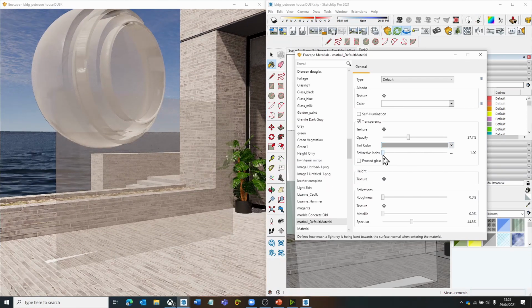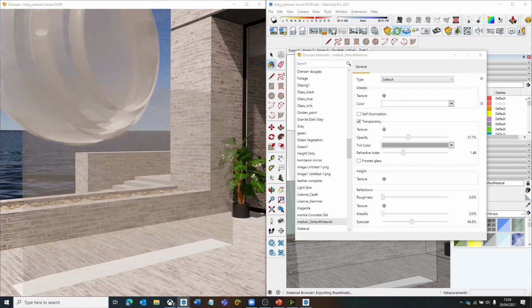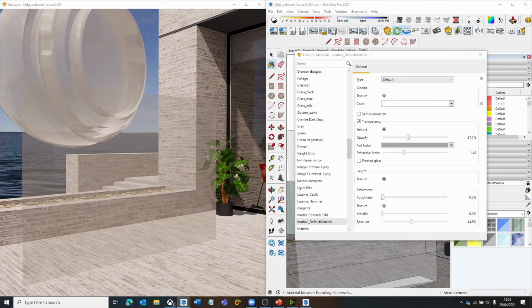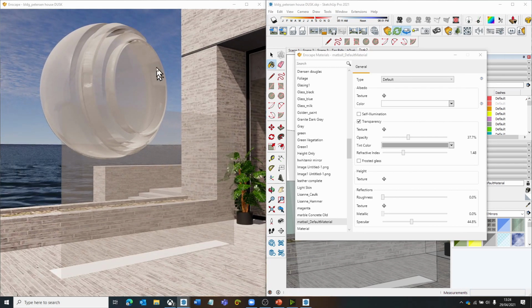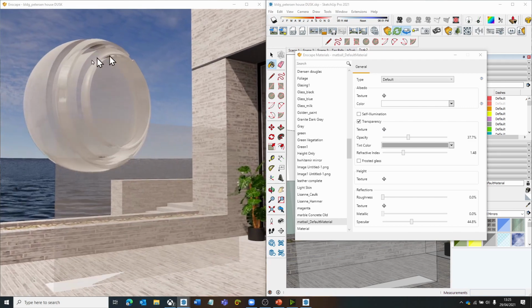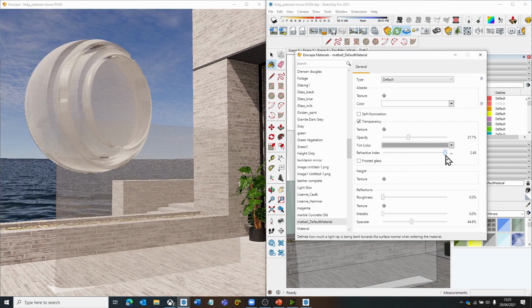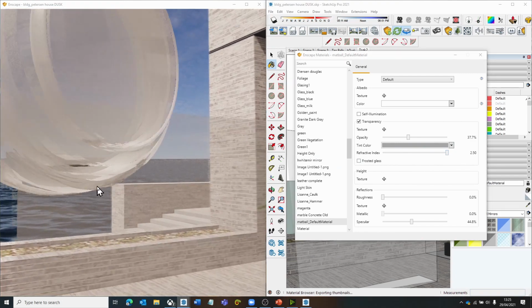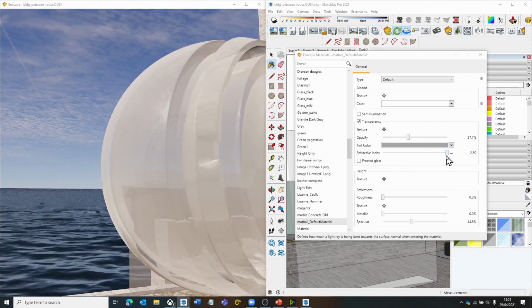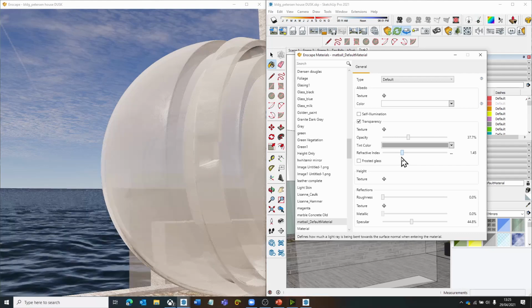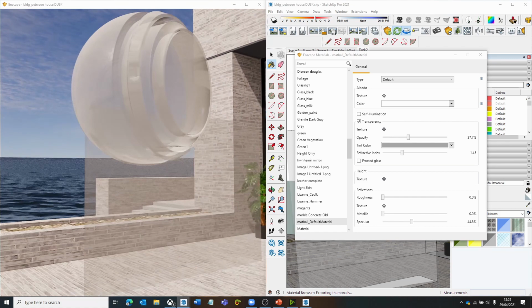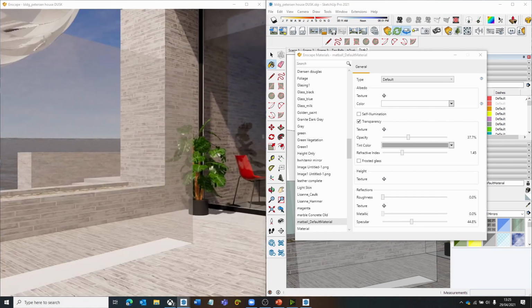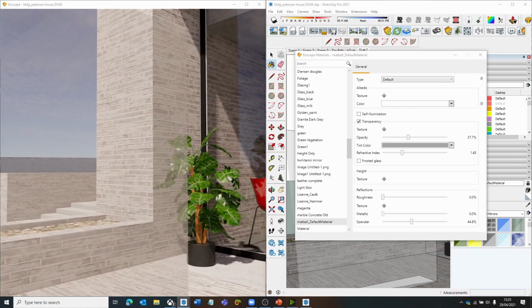Refractive index. Most things in the world should default to 1.5. Most glass will be between 1.34 and 1.49. Enscape actually treats it slightly differently for plate glass as it does to item glass. You'll see it creates that bending of light on the curved edges, almost like a double wall effect. If you're using curved objects, you might want to use that to your advantage to give it the perception of thickness, but it's not going to have any effect on sheet glass.